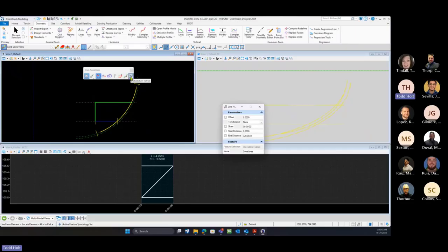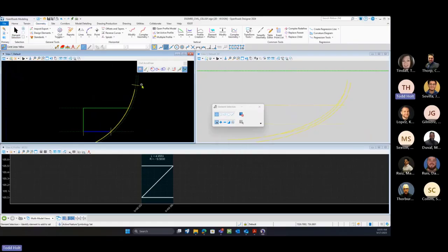Your delta station offset holds up in your civil cells. Your stationing or station offset does not. This is really the only one, and this could be your best friend in civil cells. And I'll show you the little trick that I do. Is your delta station offset here. We're going to grab our handle that we put in. I'm going to switch it back to intersection snap. I'm going to grab the handle.